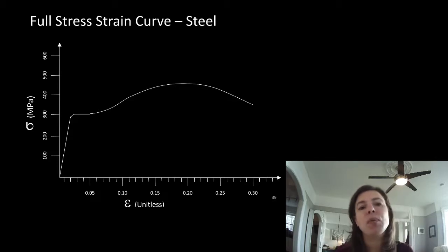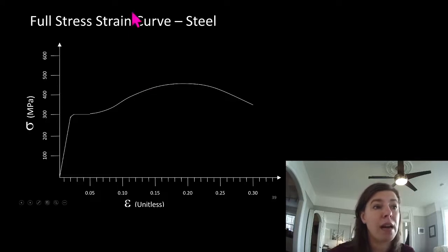Now, I said there were some terms you don't need to worry about, like strain hardening. Those are things that happen to steel, the type of steel we tend to work with, but there are different mixes of steels. The steel we tend to use structurally experiences something called strain hardening, where as we strain it, we actually get some small increase in the ability to take more load.